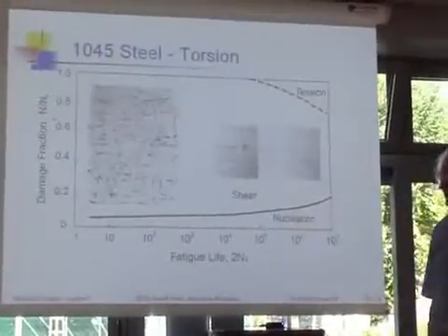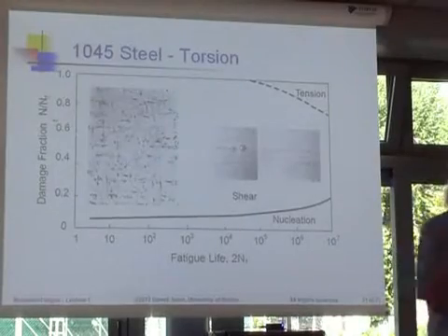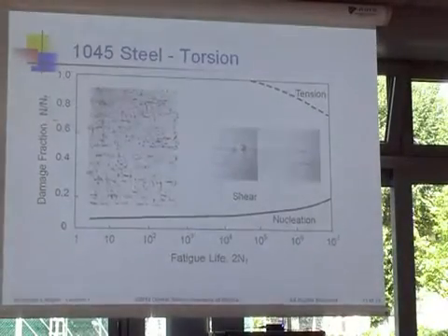Of course, the shear stress in torsion is huge. So remember, the shear stress in torsion is equal to the tension stress. The shear stress in tension is only half of the tension stress. We'll see that in a few minutes. So the cracks always nucleate, but they don't grow very fast. And that was my reason for showing you the pictures.